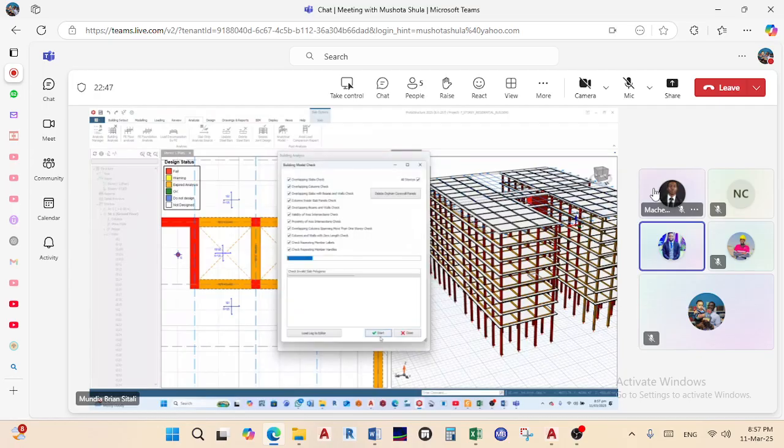Let's see if we're going to see only 14 errors. Yeah, so we have 14 errors now. So we've cleared 2. So number of errors is now 14. So similarly, if we go to story number 8 again, we should sort out this overlapping again. So we had 16, huh? Now we have 14.